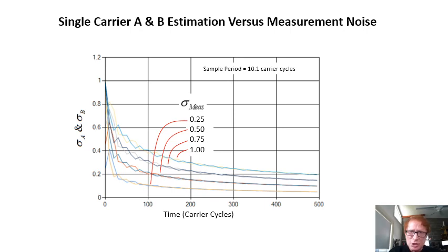The initial uncertainty in A and B is assumed to be 1.0, and this is used to initialize the covariance matrix at the start of the digital processing. This tells the Kalman filter that the A and B values are almost completely unknown. The estimation process reduces these sigma values as the sampling occurs.